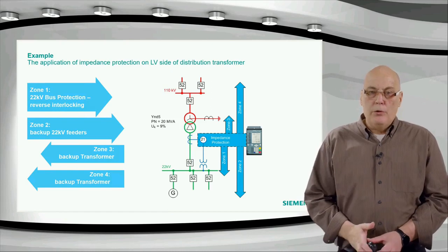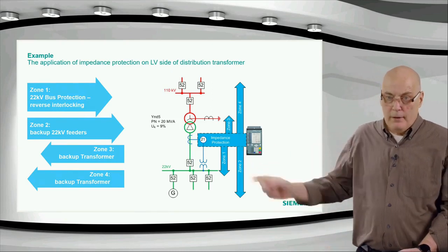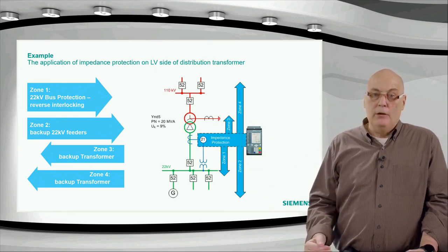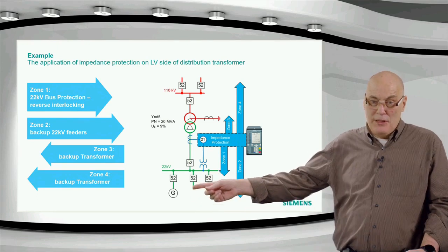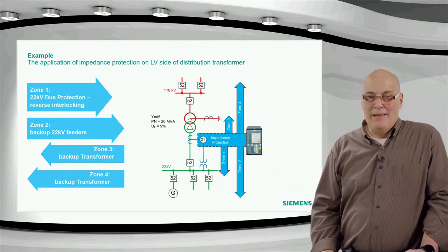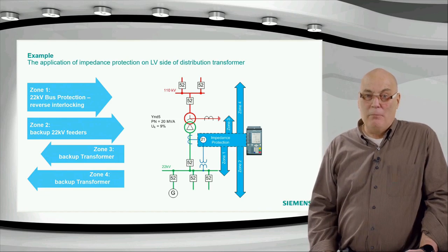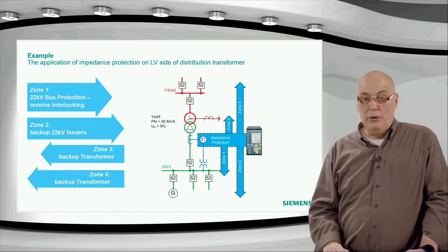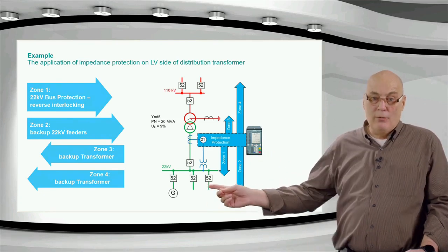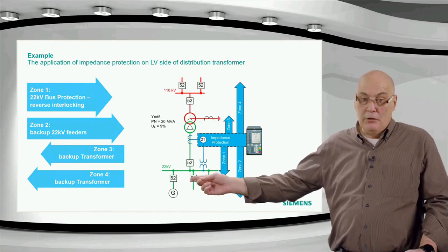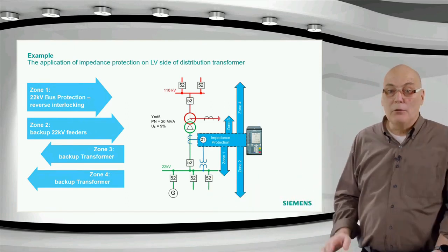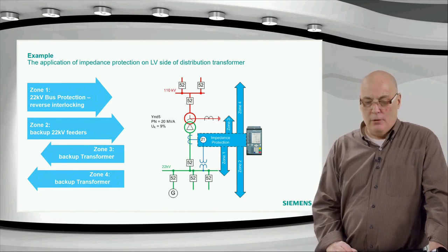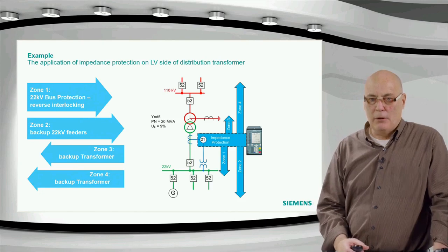An example I'm going to use to show this is what you see here, a typical medium voltage transformer. This example, 20 MVA, and you'll find that typically, especially with the renewable generation in the bottom here, these transformers are reaching their limits, and nowadays, in this environment where it used to be 20 MVA, one goes up to 40 MVA to make allowance not for the consumption but for the generation, which creates new difficulties in applying protection. But let's go step by step and not get ahead of myself, as I sometimes do.